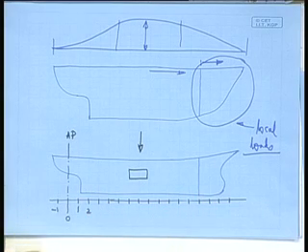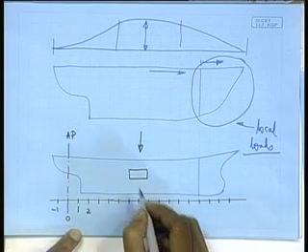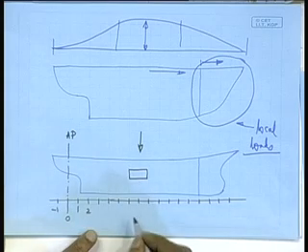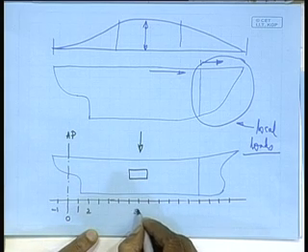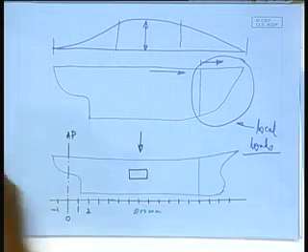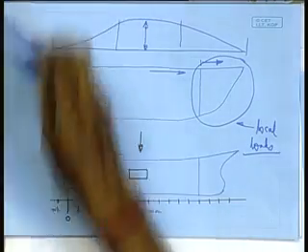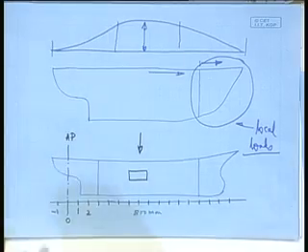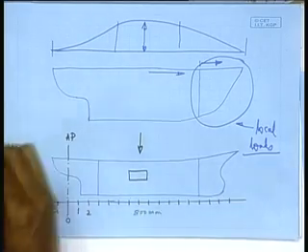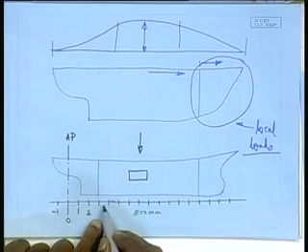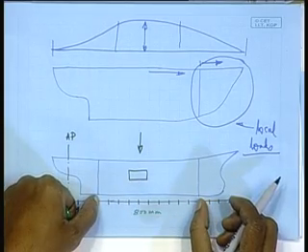And from the strength point of view, suppose for this particular vessel I take a frame spacing of 800 millimeter. So we will find the frame spacing going like this. Here you will have 800, say this is my aft peak bulkhead, and generally the entire region is 800.